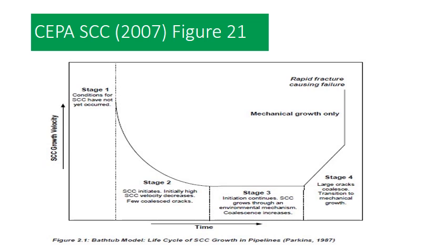I'm not going to explicitly comment on any of those different mechanisms, but I will say that when I plot my dK/da against a curve, I see something that looks very, very similar to that bathtub model. And to me, as a fracture mechanics person, it just seems more than coincidental that things would play out that way. So I'm going with the observation that the bathtub model very similarly matches my crack stability expectations, simply based on the K gradient.